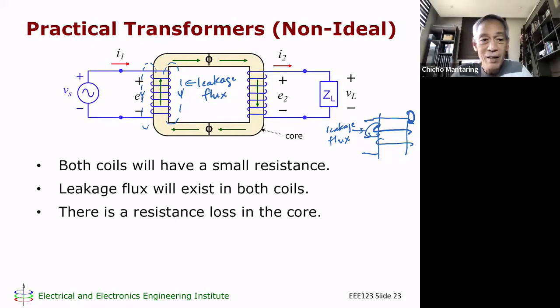Some of you, your stoves at home may already be induction. Instead of heater coils, you have induction coils. And what these induction heaters do is make the thing you cook in the core. Your cooking pot or pan acts as the core, and it creates eddy currents to flow in your pot, and that causes your pot to heat up. That's the principle of induction heaters.